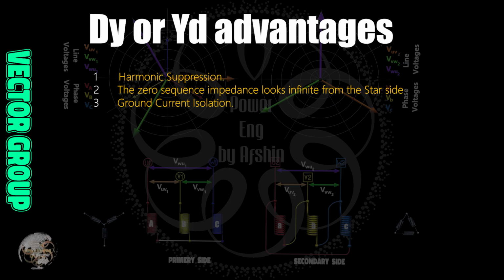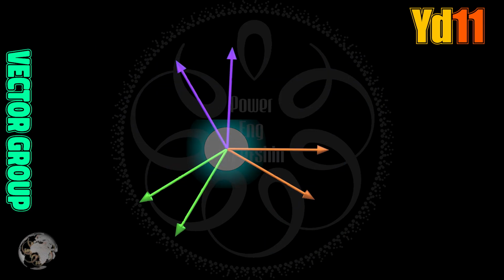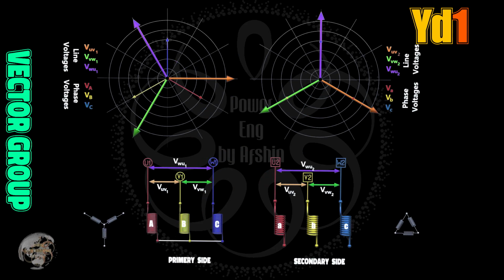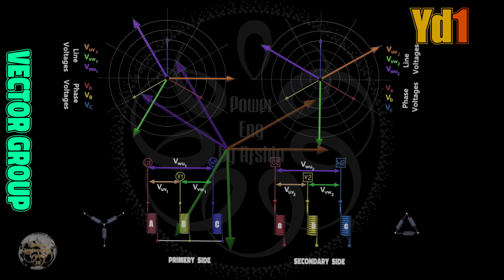A fault on the secondary side will not affect the ground protection on the primary side, which is vital for system coordination. In vector group YD11, the secondary leads the primary by 30 degrees. It has a lower inrush current than the DYN type, perfect for power plants and transmission substations. Vector group YD1 is similar, but the secondary lags by 30 degrees. The choice between 11 and 1 depends entirely on matching the existing transformers in your network for parallel operation.